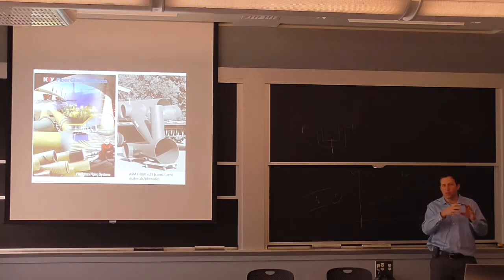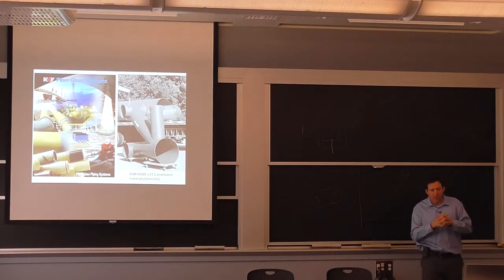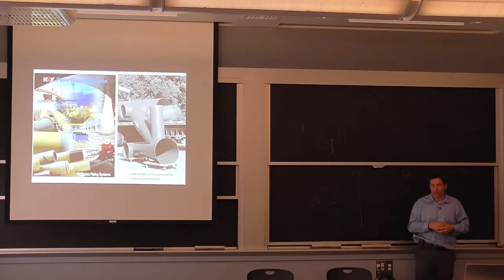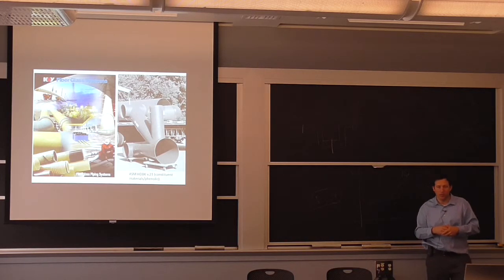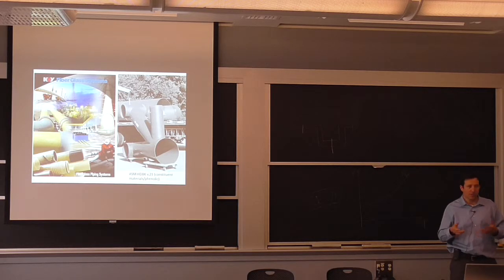So if there's a section of a chain, instead of creating a chain reaction where now you have more and more breaks, it encapsulates it. So the amount of that antioxidant that you put into your polymer in the first place when you manufacture it makes for the life of that polymer. So if you put a small amount, maybe you're going to resist the weather 1 or 2 days. If you put more, you can do 10 years.